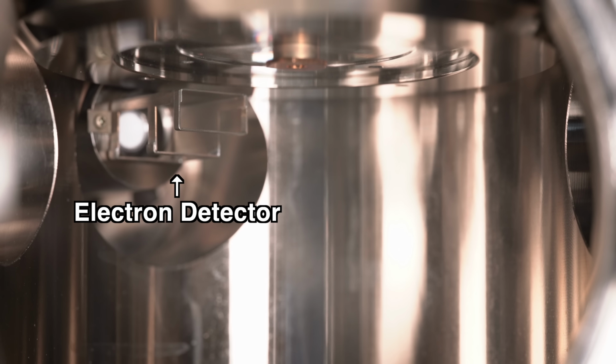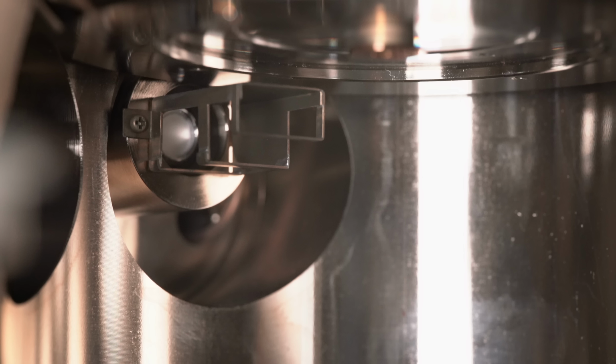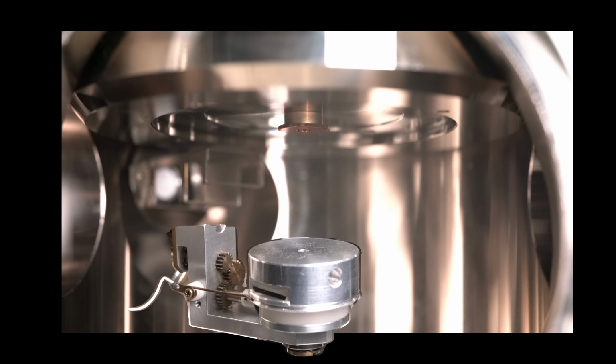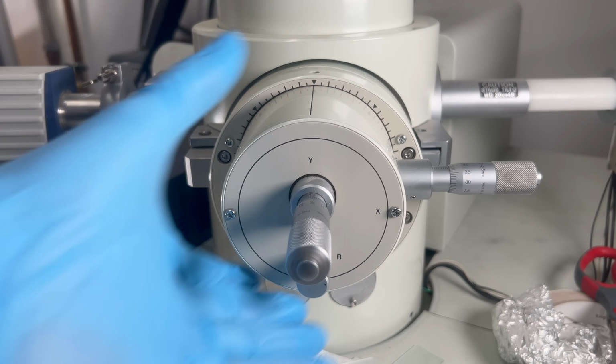Lastly, we have the secondary electron detector here in the corner. Fortunately for us, this component is so far away that we don't really have to worry about bonking it. Really, the only critical measurement here is the distance from the top of the sample holder to the bottom of the objective lens. The only problem is that we can only measure that distance with the door closed.